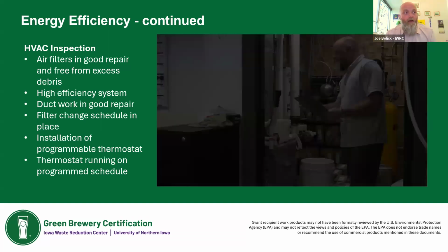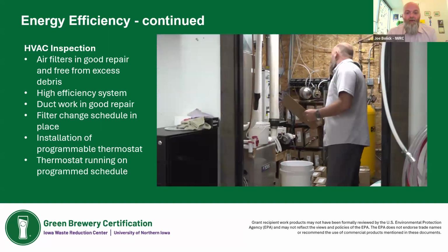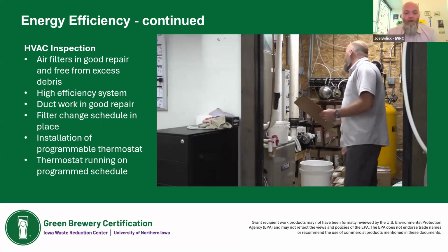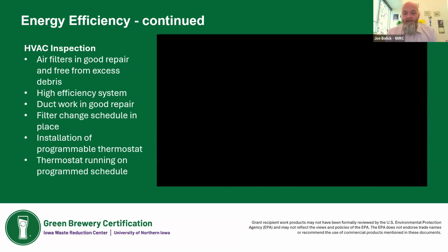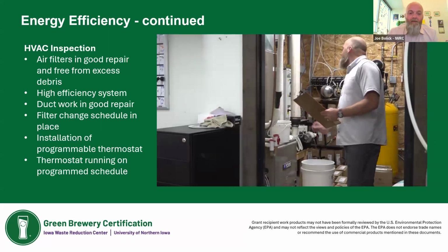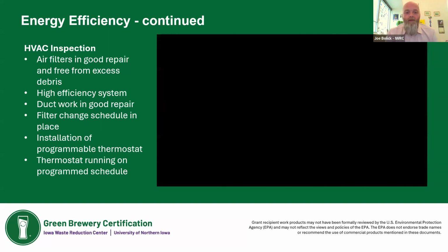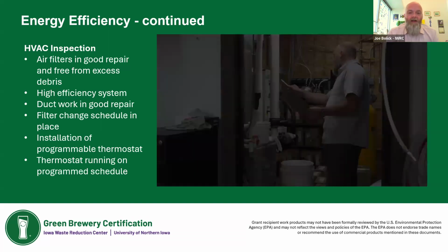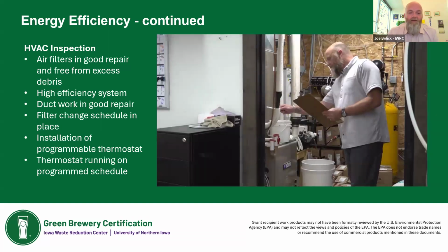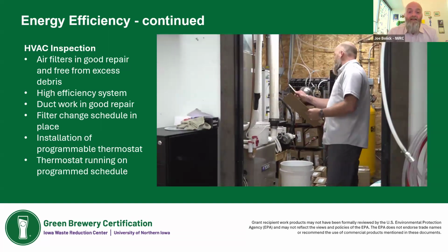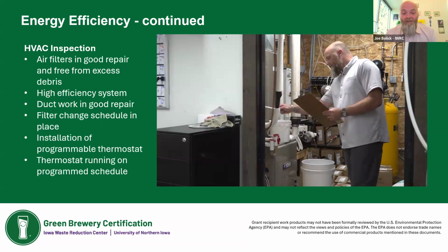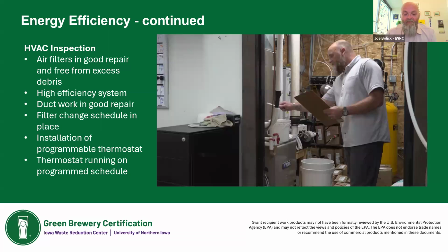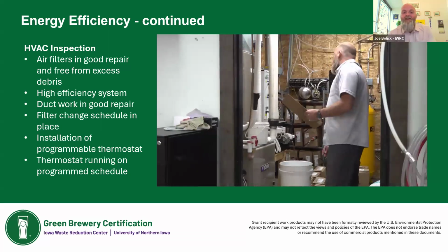And then the other one we usually end up having to laugh about is looking at thermostats. Almost every brewery we've worked with does have a programmable thermostat. The next question is, is it actually programmed? You'd be shocked how often they spend the money on a programmable thermostat and then just set it to run at the same temperature no matter what. We've found that happens quite regularly. So we'll sit down with them and go through the process of getting it programmed. What are your business hours? What do you want? How do we do this? And we get them actually using the thermostat with all of its capabilities to optimize their efficiency and lower their energy consumption.